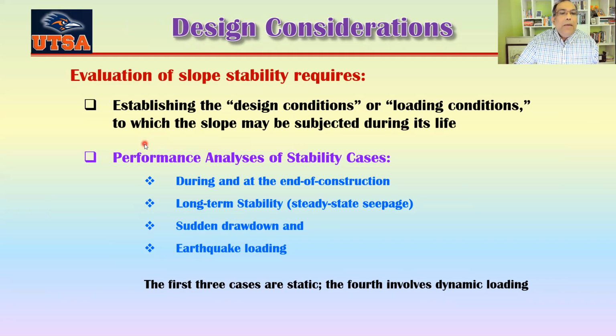And then I must also include the performance analysis of stability cases. If you talk about the stability cases, during and at the end of construction, we usually call that short-term stability. Then we have long-term stability, which means steady state seepage will be established by that time.